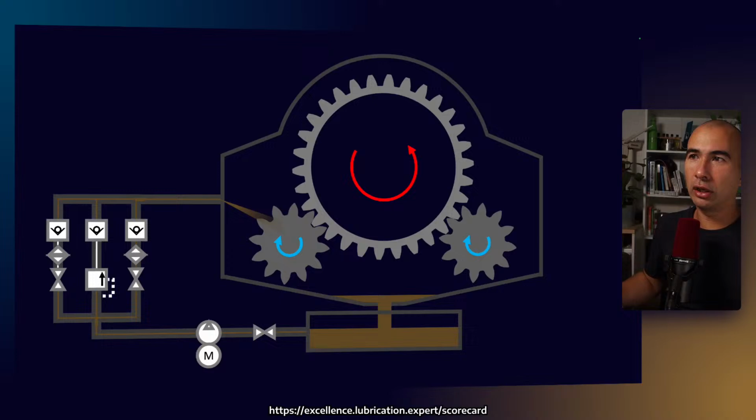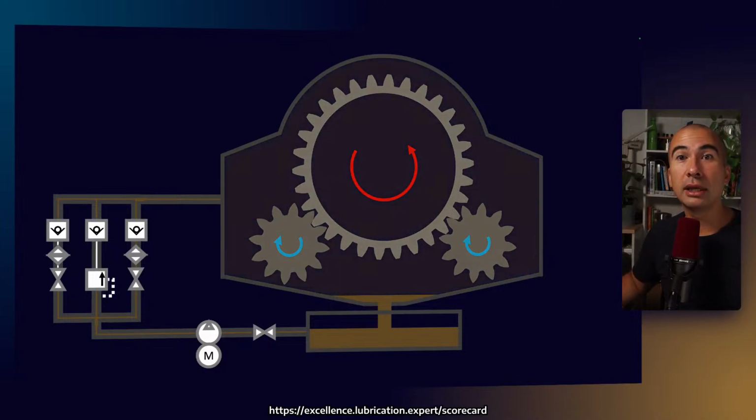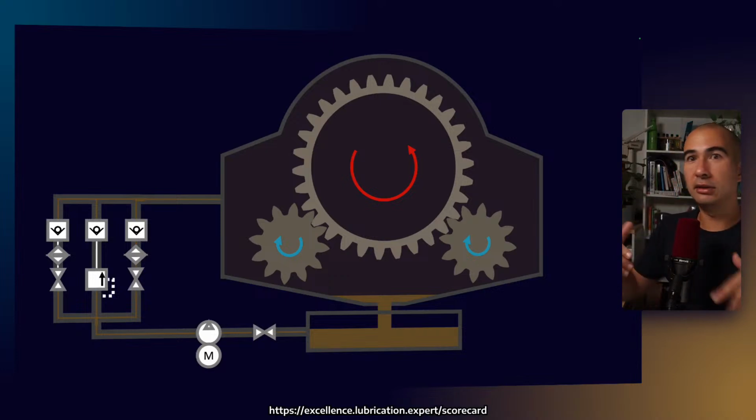The advantage of circulation systems is that obviously you can filter the oil as it gets redistributed back to the gearbox. Another type of lubrication is mist lubrication, where we generate a fine mist that would go onto the inside of the gearbox. This has a couple of advantages. Number one, we know that all of the components are going to get lubricated. But number two, because there's some positive pressure on the gearbox, it's actually going to keep out contaminants like dust and water and all that sort of stuff because there's positive pressure inside of that gear casing.